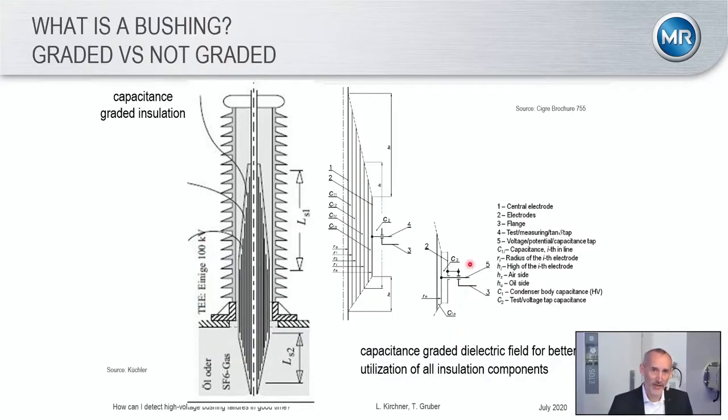And that's the difference. So the insulation system here is designed for higher voltages. Usually, according to the standard, you have to test this voltage tab with 20 kV AC for 1 minute. This measurement tab is only tested with 2 kV for 1 minute AC. So you see the difference here in the voltage. And as I mentioned, this design is usually seen in North America.